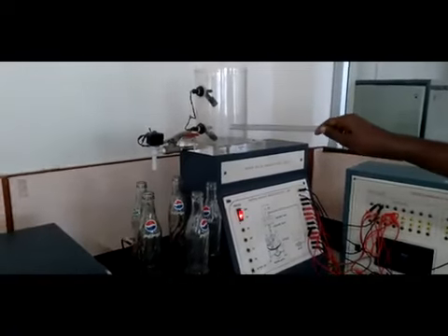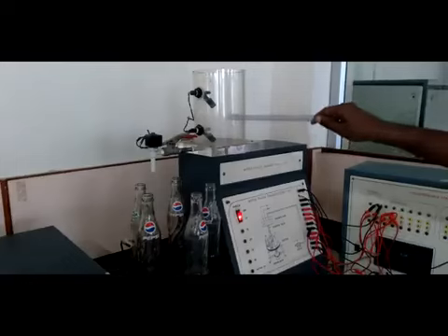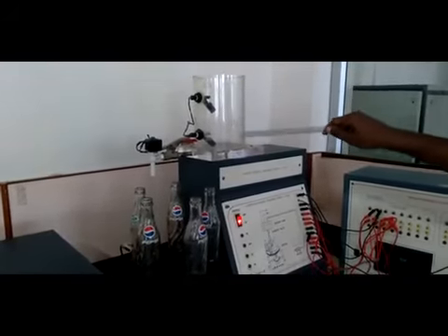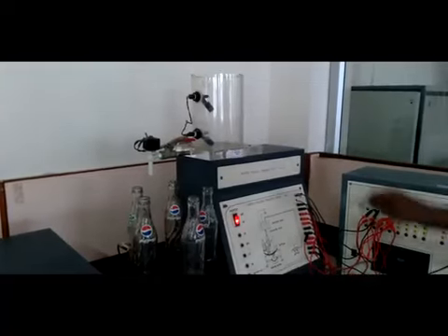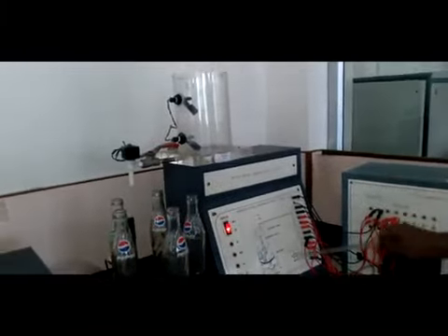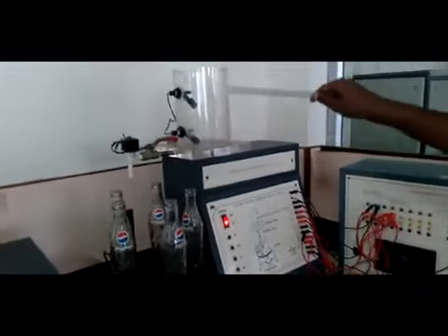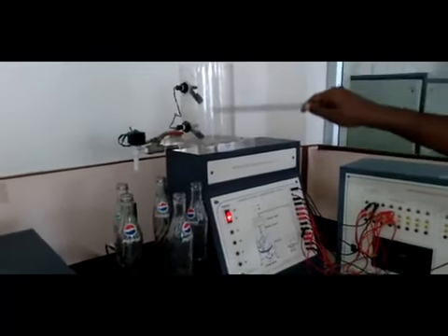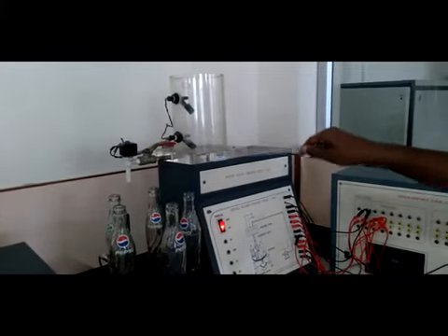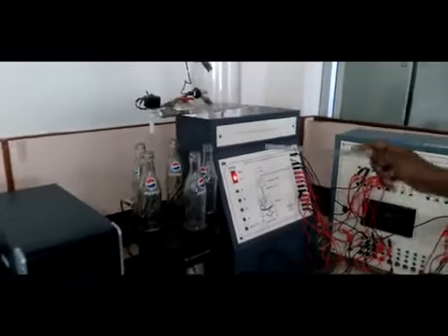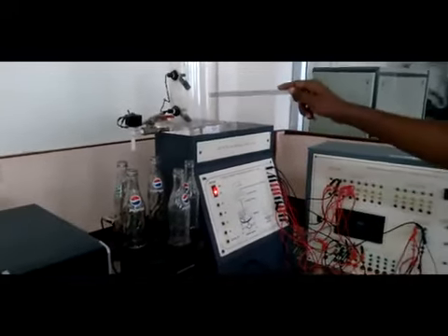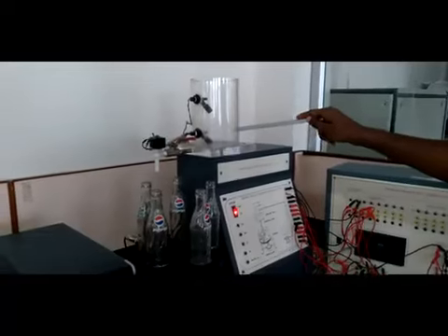When the low level sensor is false, it indicates that the required level of fluid is not available in the tank. What will happen then is the motor will work and fill the tank. When the high level is reached, the motor is stopped. That is the condition for this reservoir tank. If the low level sensor is true, only then will the entire process work. Otherwise the process will not work. It means for the PLC logic that there is no minimum required water level.